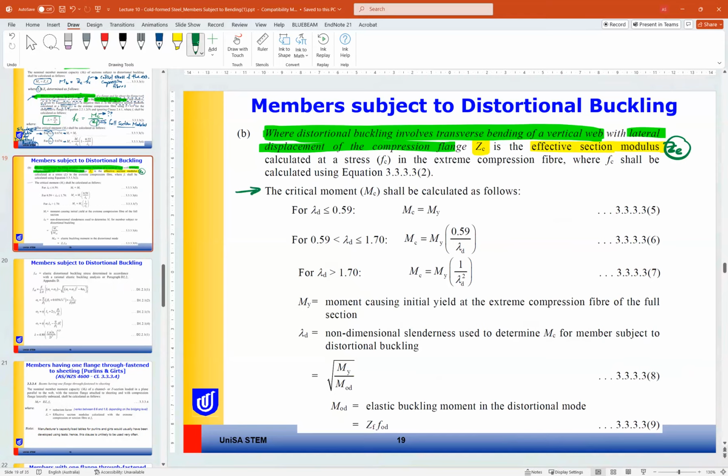And for the critical moment in this case, not only two cases, we have three cases. So again, based on what? Lambda D. So we need to find lambda D. Lambda D less than 0.59, so equal to M yield; more than 1.7, M yield multiplied by 1 over lambda D squared. And in between, it will be My multiplied by 0.59 divided by lambda D, where My again is the moment causing initial yielding.